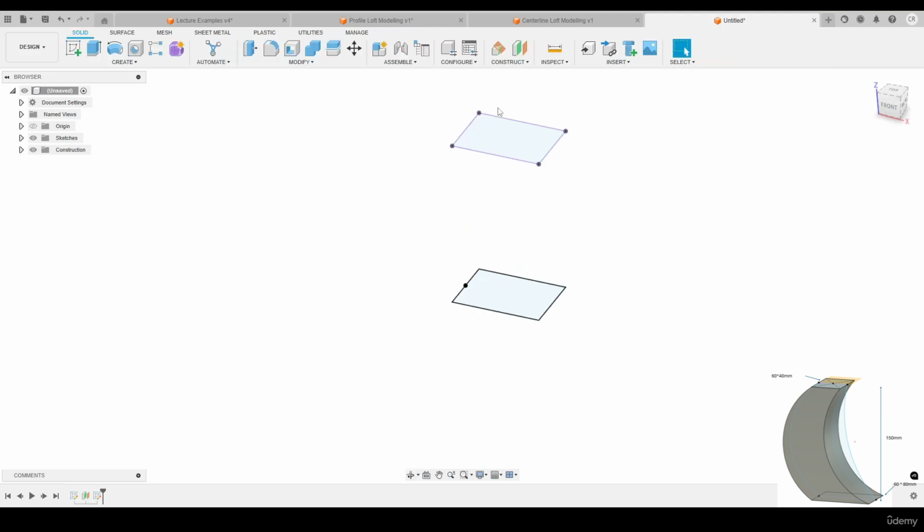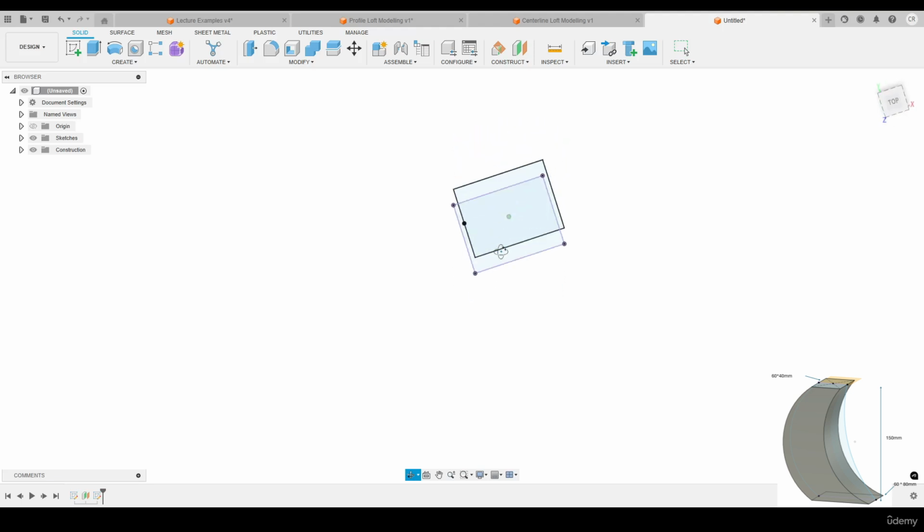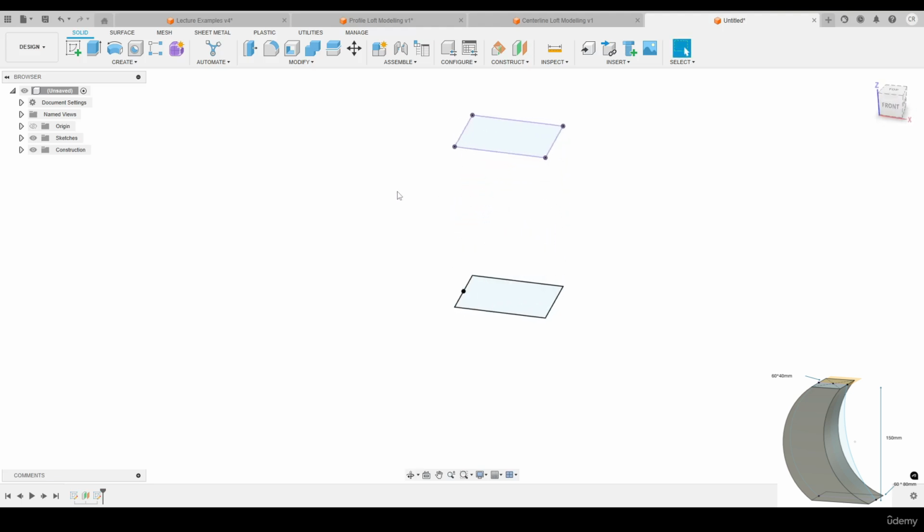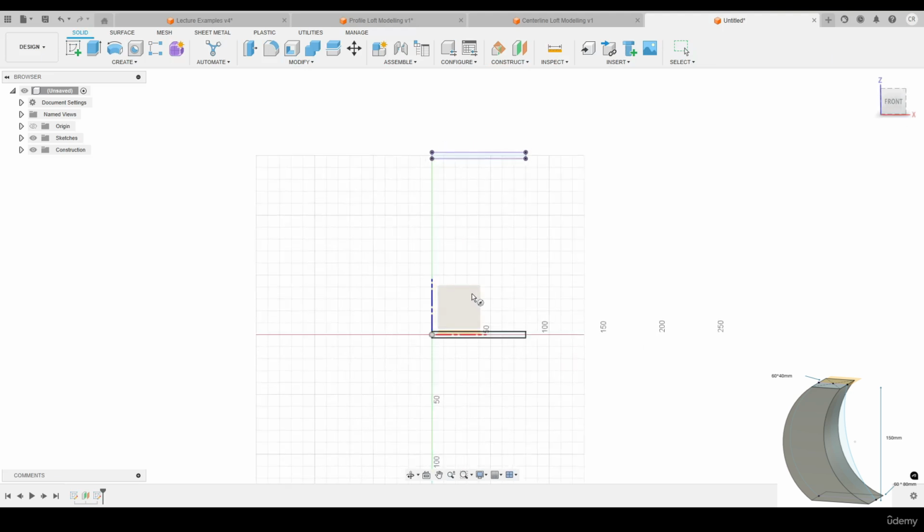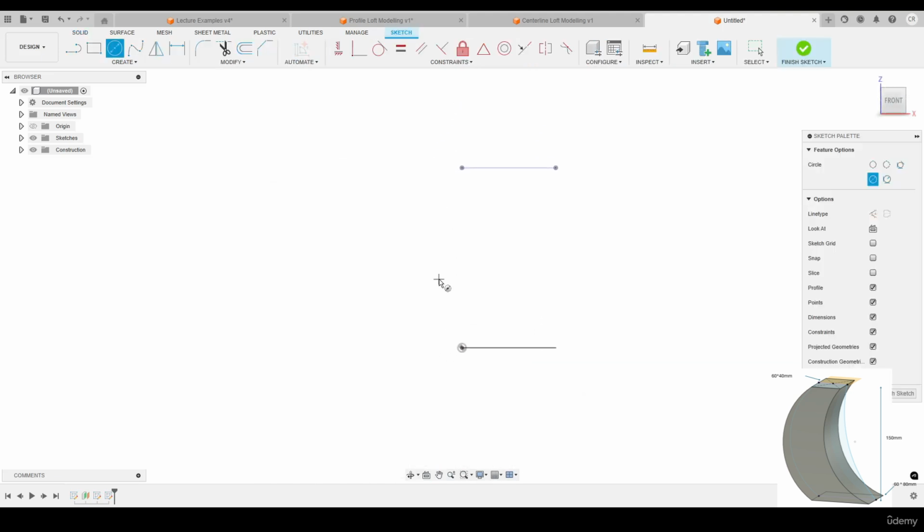So if we go ahead and loft between these now, it will just be as easy as doing an extrusion, nothing interesting. But if we now go ahead and add in some guides to guide the loft in its direction, it will show us something quite unique. So let's hit C on the keyboard and let's do a sketch on, let's go for the XZ plane. And in this case, I'm going to use an arc. Now let's use a 3-point arc. One note about when we're using rails, they must be to some extent smooth. I.e. if we've got a really jagged line, Fusion will not be able to carry out the loft as the faces will be too complex and perhaps conflict with one another.